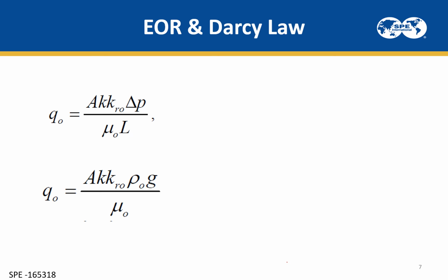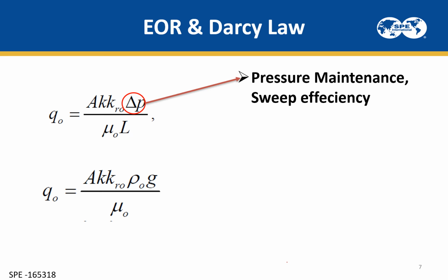One of them is area multiplied by permeability multiplied by differential pressure, over viscosity multiplied by the length. And this can also be converted to rho g h. So when we are focusing on the differential pressure, that means we are looking for pressure maintenance and sweep efficiency, which will also improve the productivity of the oil.